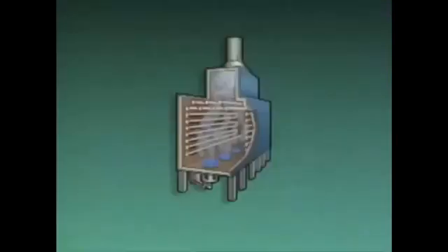We've just looked at airflow problems related to air leaks and to insufficient air at the burners. The next example is actually a combination of these two problems. It's called afterburning. Afterburning can occur when you have an air leak in the convection section at the same time that you have too little air at the burners. If there's not enough air at the burners, unburned fuel gets carried into the convection section. Then if you've got air leaking into this section, it can combine with the unburned fuel and ignite, which could cause a lot of damage.